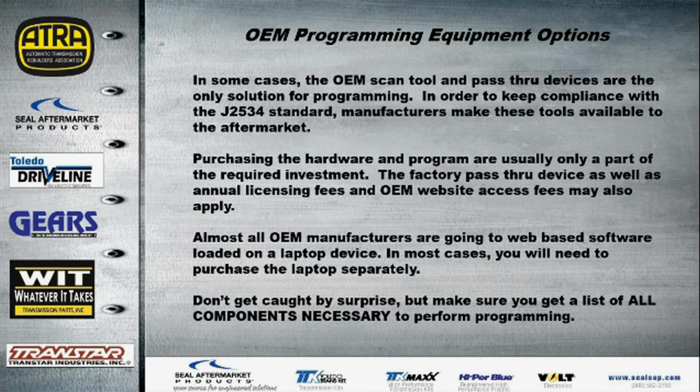Most of these packages now are software driven, so we're not actually purchasing a hard tool anymore like in the past where we were buying a Tech2 tool or a DRB3 tool. We don't have to do that anymore. All we have to do is provide the laptop per the OEM specifications. So again, it's a very different world we're coming to here. Almost all OEM manufacturers are going to this web-based, software-loaded laptop so that they don't have the hardware to deal with and update anymore.